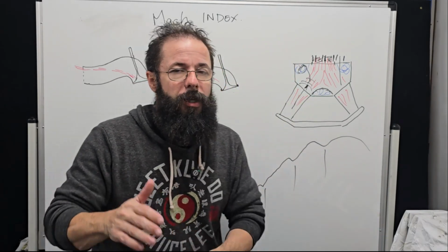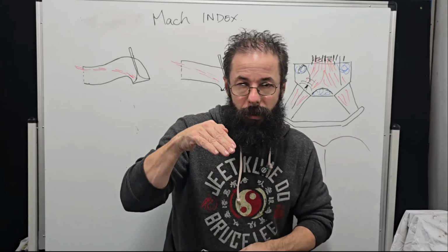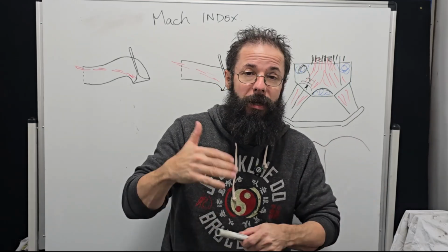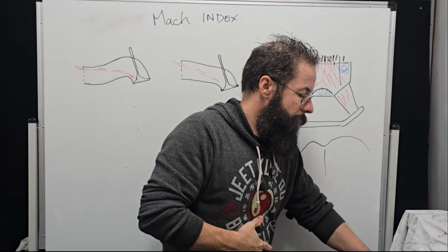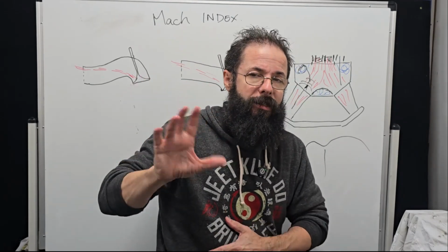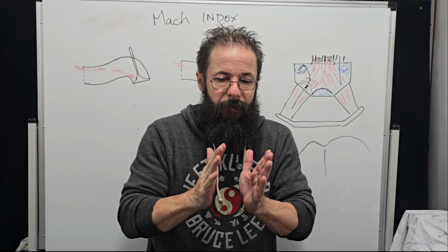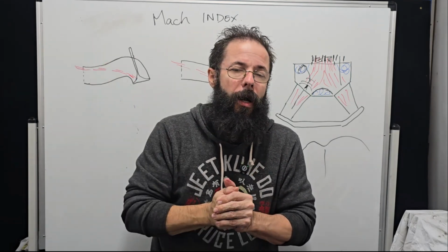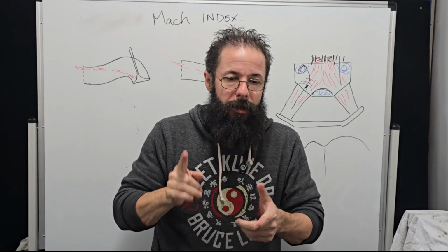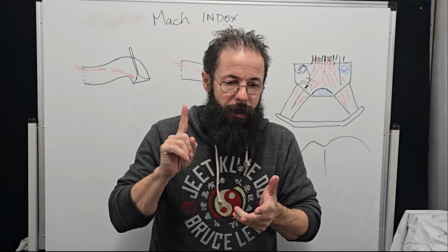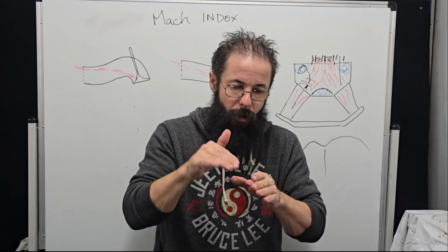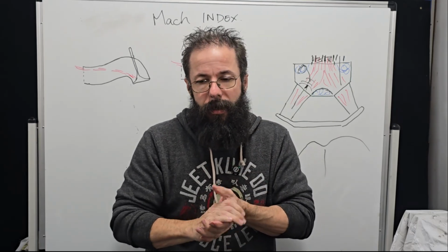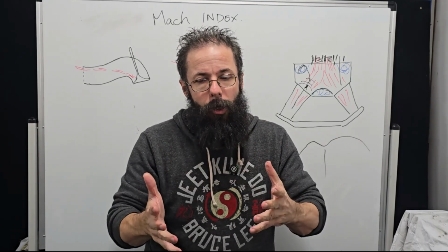The good thing about ITBs is torque on demand, right? We can adjust the throttle, increase the airspeed in the runner. I might have to do a whole series on ITBs and talk about even placement. We found that the further we went away with the throttle body, the more horsepower the ITBs would make, and the more stable that air column was, because the throttle plate actually creates turbulence, or more turbulence, I should say.